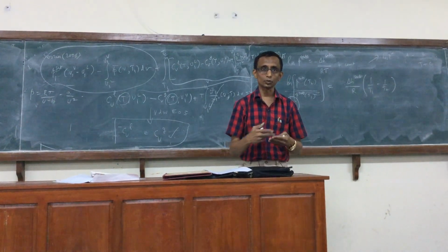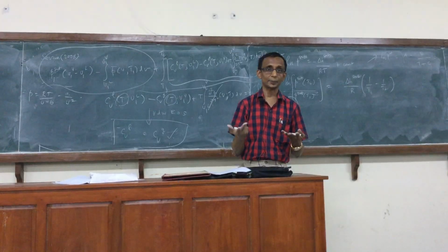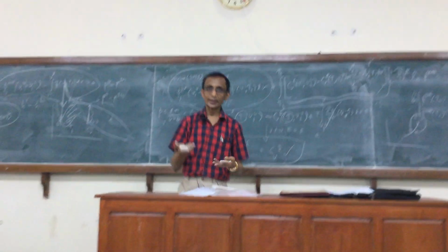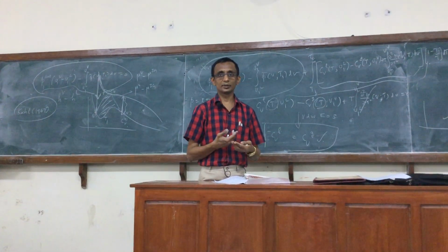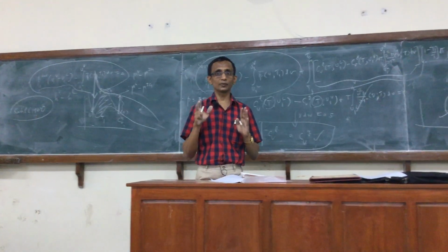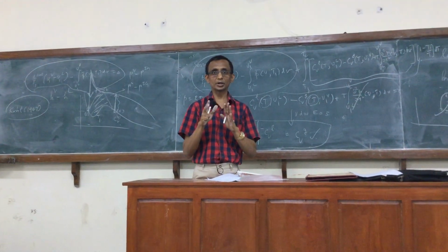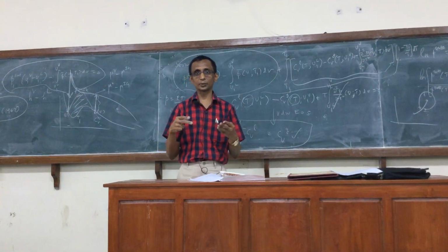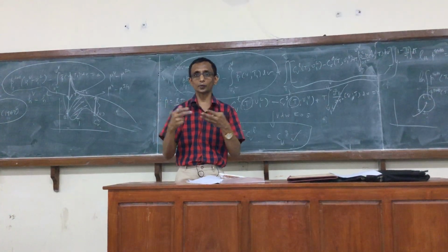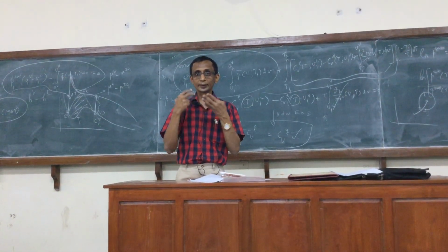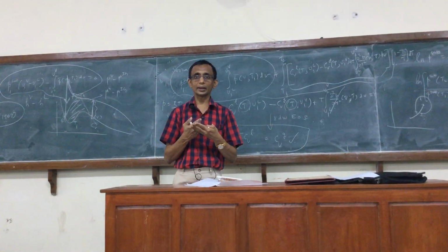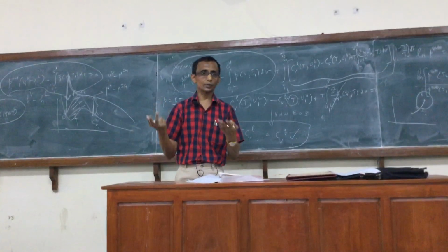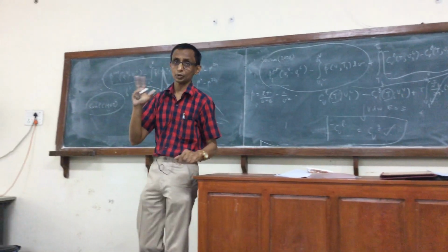It is a property exhibited by a substance. I can't give an example; it's a description. Why that happens, you have to go to the molecular level and see. But the phenomenon that you observe and should remember is that as you reach the critical point, all along you will have two phase coexistence. The properties of the liquid and vapor are moving closer and closer to each other, and at the critical point, they become identical and you can't have two phases beyond that. It means only one gas phase, sir. Gas, you can call it, yeah.